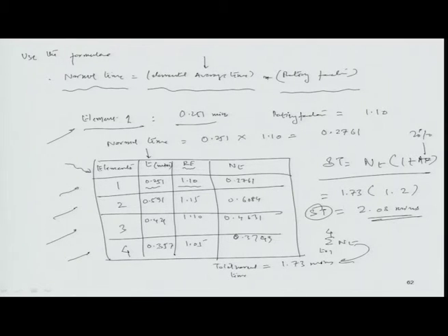So, an operation which is comprised of 4 different task elements, having individual components of their normal times based on the operator efficiency, the average operator efficiency, is mapped in terms of the standard time which I will finally assign to this particular set of 4 elements constituting one particular job. That is how we do the time study.